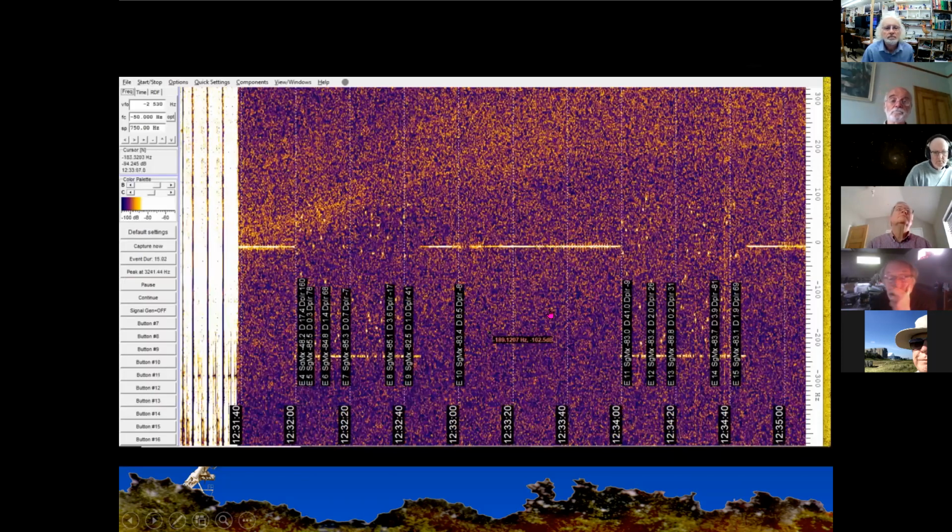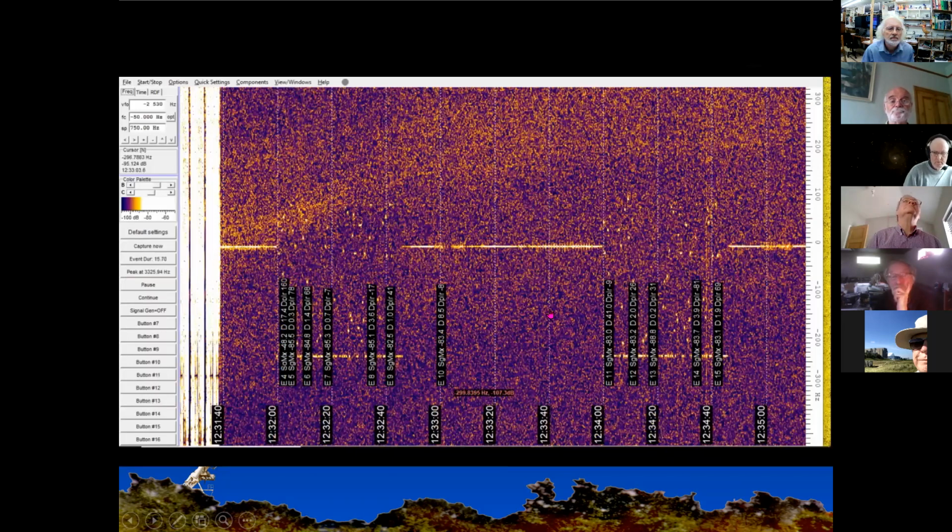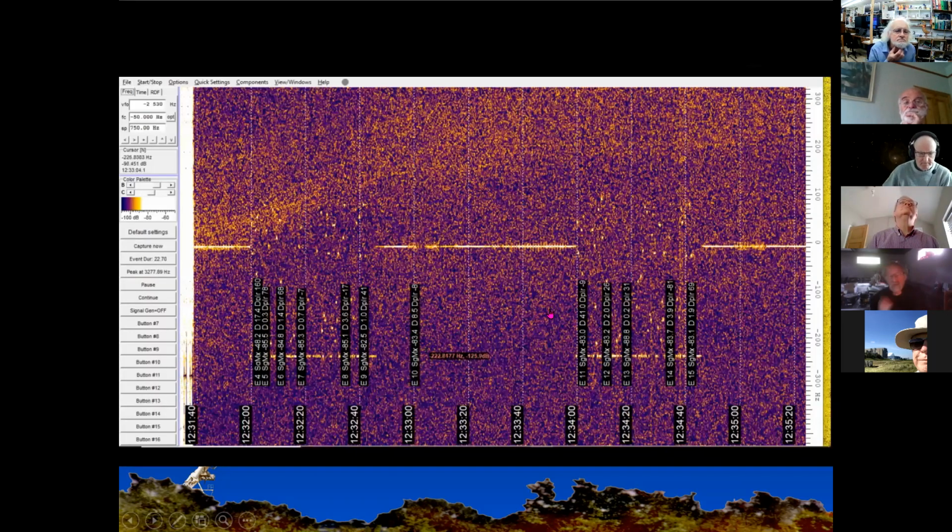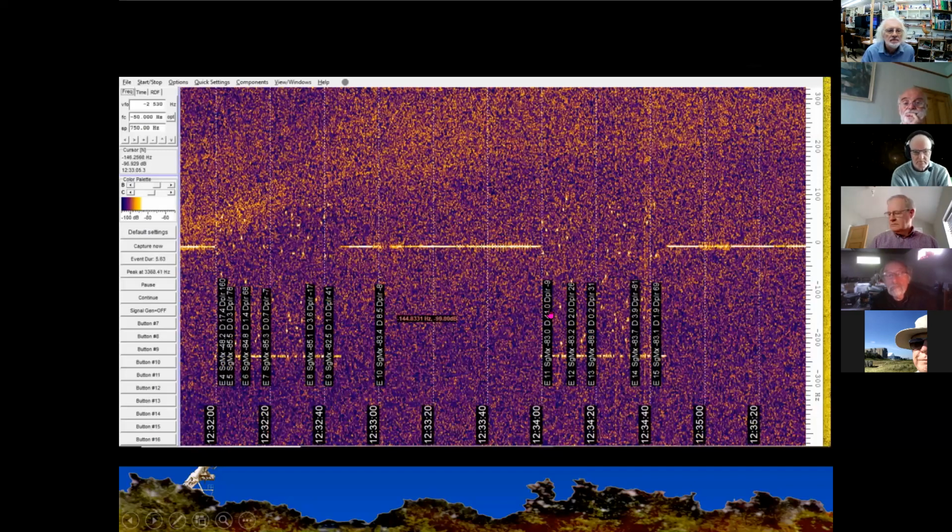The message gives a serial number, an event number, which is reset at the start of each hour, the amplitude of the signal at the start of detection, the duration, which is a bit problematic with this particular signal, and a measurement of the Doppler shift. So the Doppler shift we're showing is -8 Hertz for the carrier. If we get into the tone sequence, we'll see that the Doppler shift values are going all over the place.